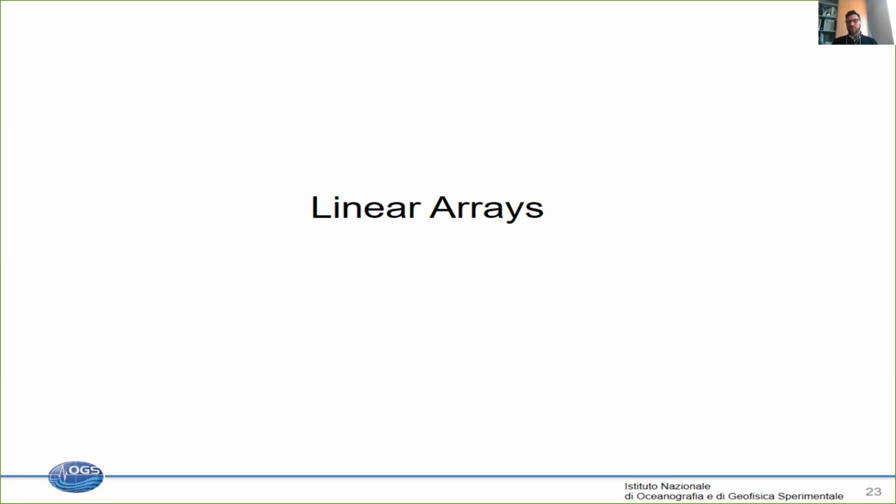We know that if we know the profile or the structure of the underground, then we can, in some way, try to calculate the site response through numerical simulation, that can be from very simple, in simple 1D, to 2D and 3D, and so on. Okay, these are just some of the tools, and if you remember, we also introduced shortly some information about inversion. So using the inversion and the information that we get from the H/V, we can obtain the shear wave velocity profiles.